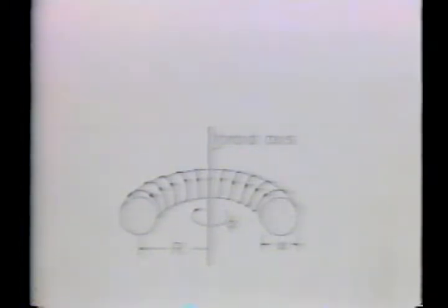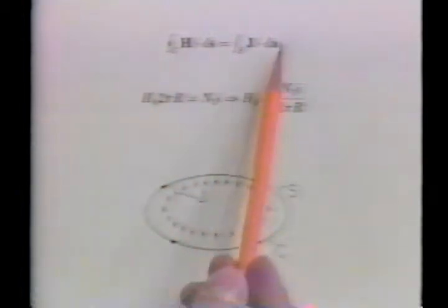Ampere's integral law is written for a contour C circulating about the toroidal axis within the core. Because the major radius R of the torus is large compared to the minor radius, the field is essentially uniform over the cross-section of the torus. We approximate the average radius by the radius R. Thus, the line integral of H is essentially 2 pi r times H.